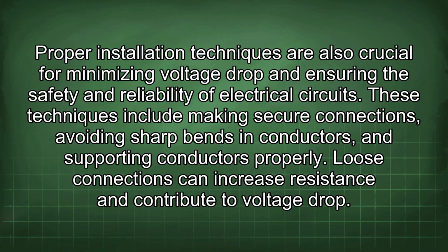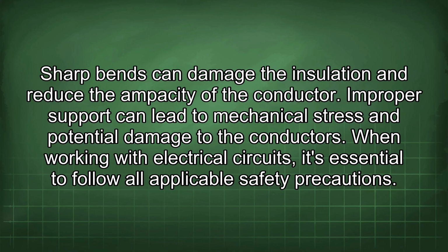These techniques include making secure connections, avoiding sharp bends in conductors, and supporting conductors properly. Loose connections can increase resistance and contribute to voltage drop. Sharp bends can damage the insulation and reduce the ampacity of the conductor. Improper support can lead to mechanical stress and potential damage to the conductors.